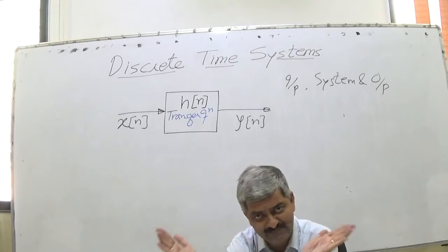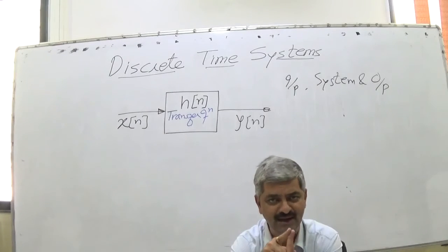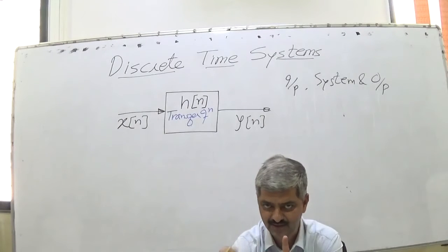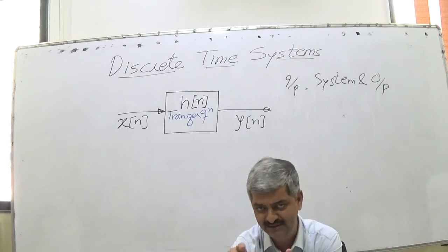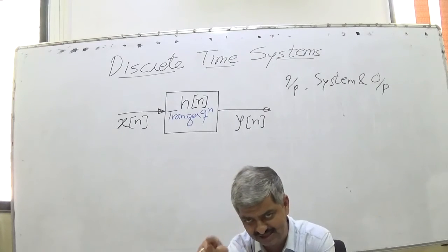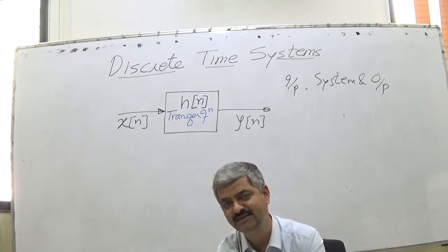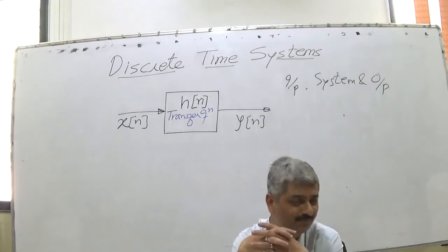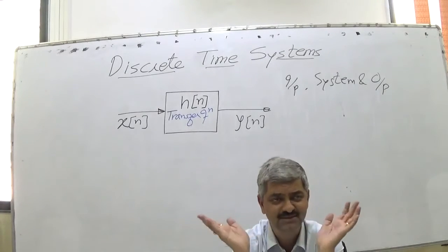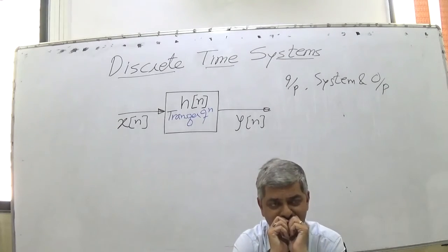But everything between these two, after the mic, is some kind of signal conditioning using a small amplifier, then ADC, entire digital processing, and its output goes through DAC to one amplifier and the speaker. So what has happened now?